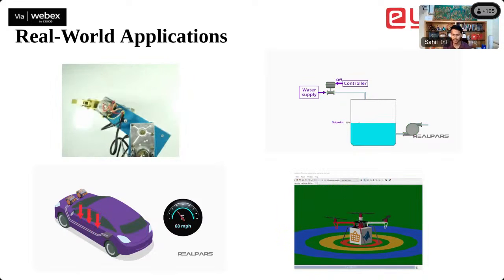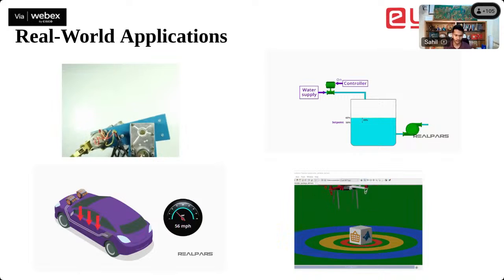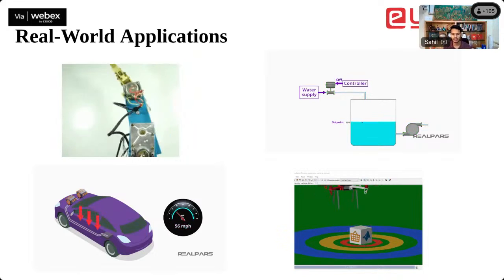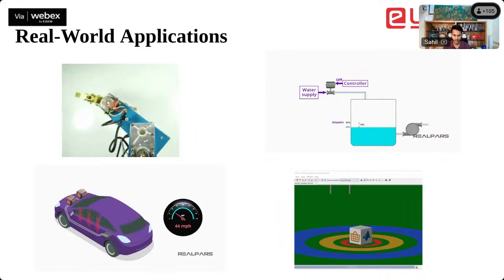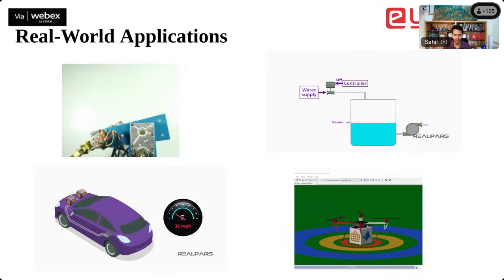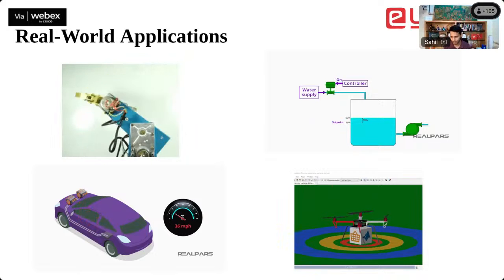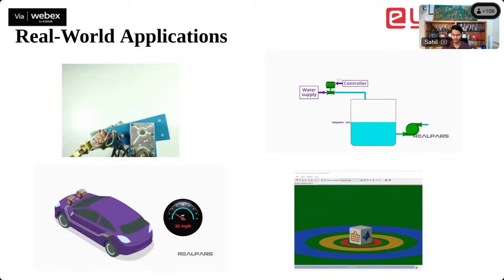If the D-term responds to every tiny jump in the data, your system will be very shaky. To prevent that, we filter the D-term. In simple words, instead of reacting to tiny movements, we look at a more averaged value. This makes the system smoother and more stable, especially important in drones, robots, or self-balancing systems.